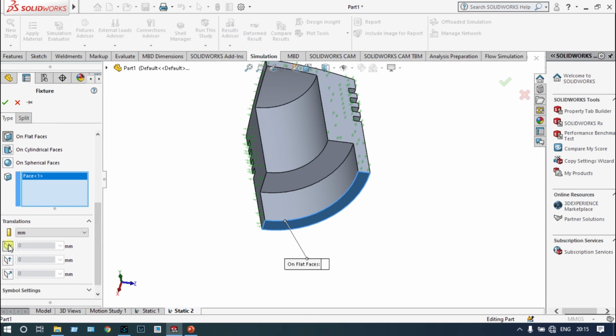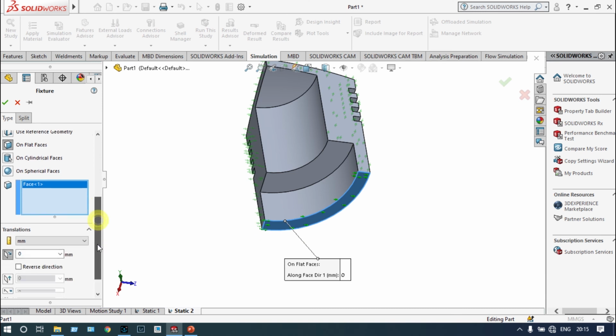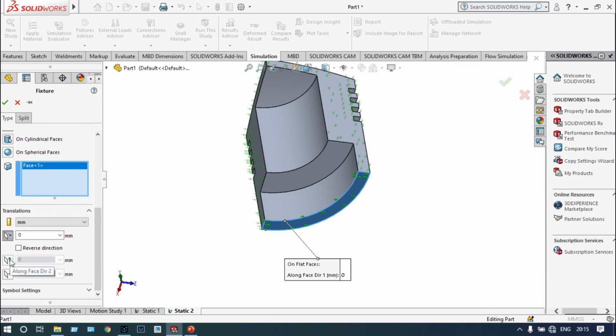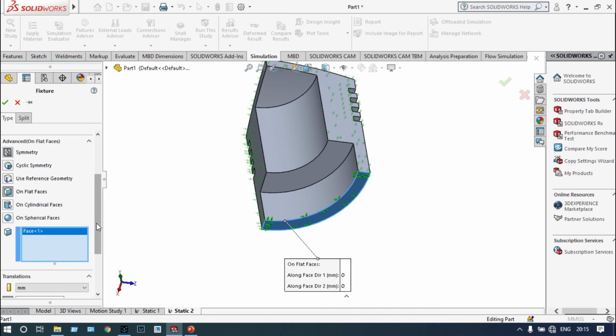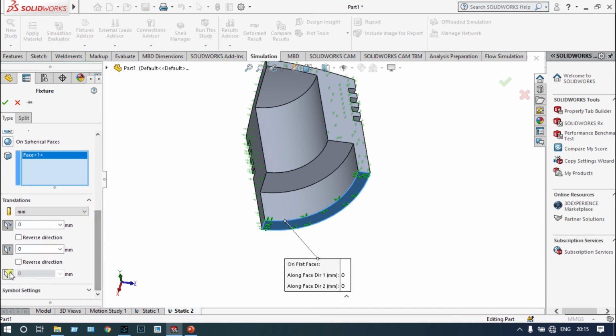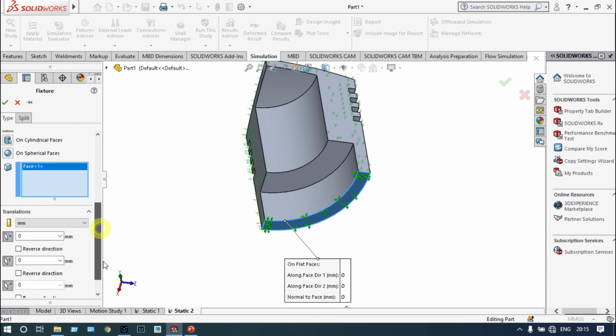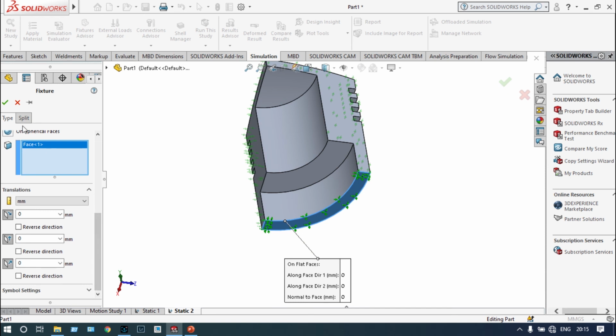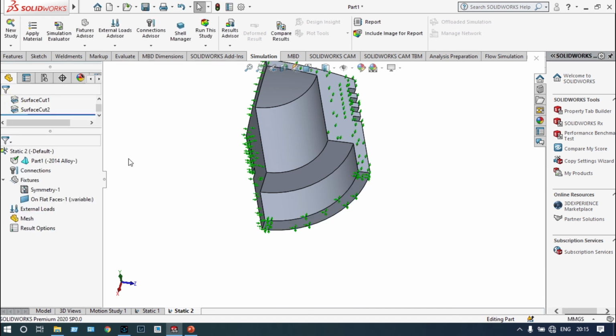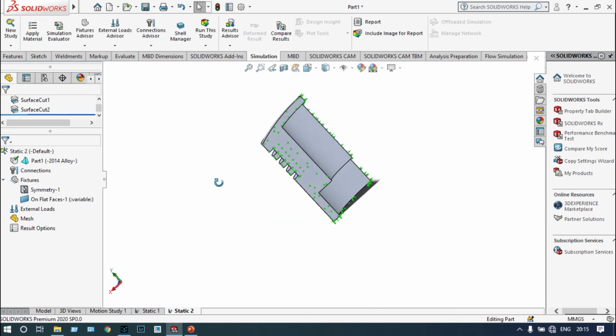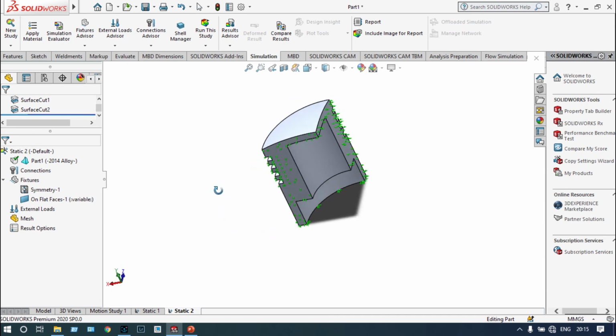With respect to radial direction it will be having 0 displacement. With respect to circumferential direction it should be 0 displacement, and also with respect to normal direction it will be having 0 displacement, right? So green check, bottom part is fixed. Boundary conditions applied perfectly.